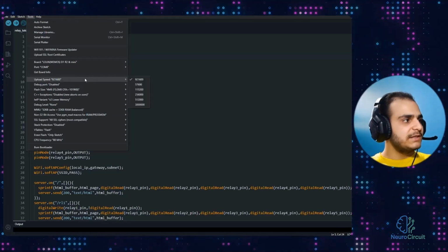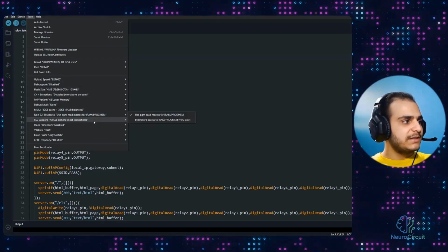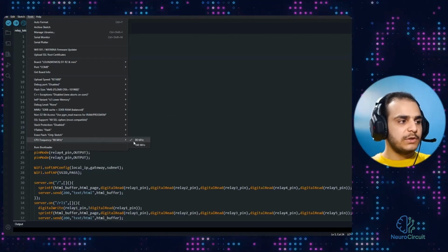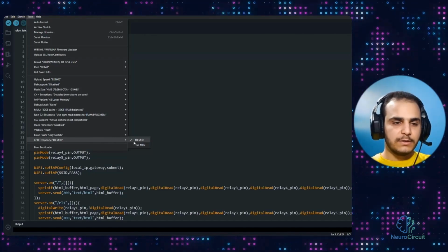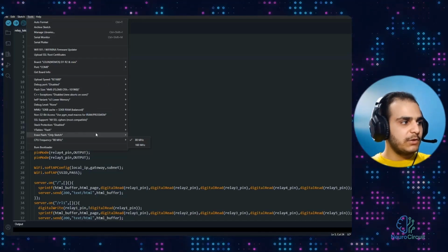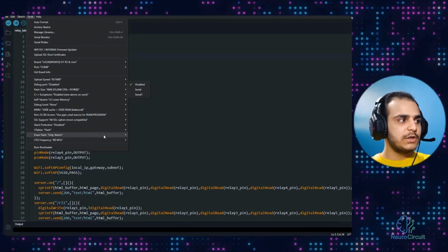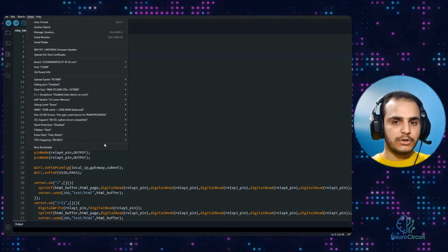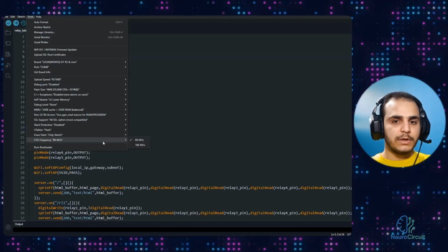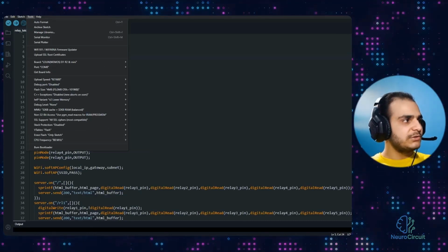These settings are for things like programming speed, memory structure, and tasks related to device clock speed. The microcontroller's default is 80 MHz, which is very important, and for most tasks, it's sufficient. You don't need to switch to 160. 80 is completely enough. So try to go through your initial lessons with these settings, and then we'll get familiar with these options later, or you can look them up yourself. They're not things you'll be dealing with every day. They're more specialized topics that we don't want to get into right now.